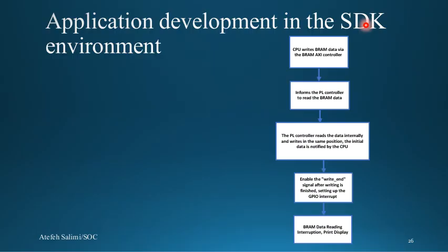You know that first of all, in the SDK environment, you have to create a board support package, and then create another application project and link this application project to the board support package that you already created. And when creating the application project, you could choose between different templates available in SDK. For example, Hello World is the simplest and basic design that you could edit.